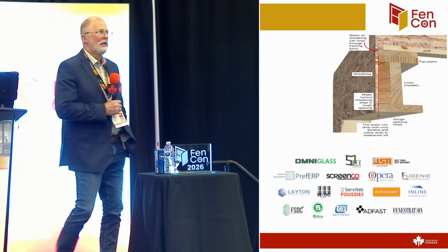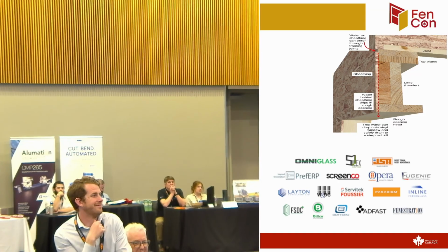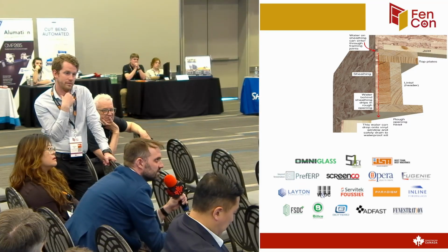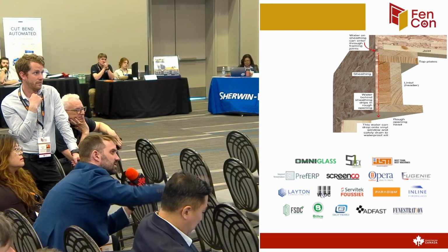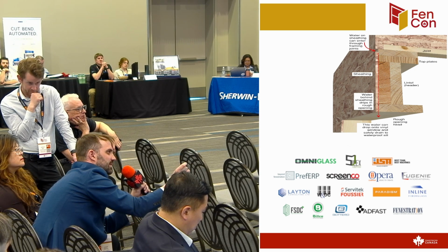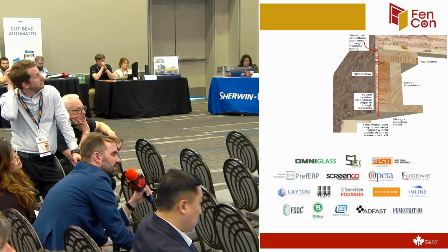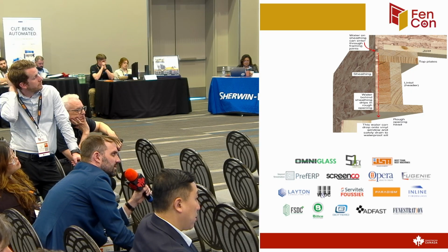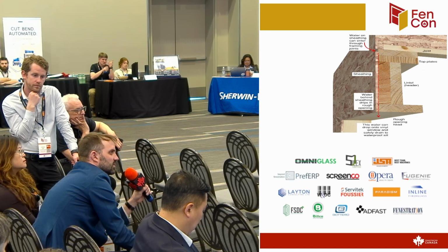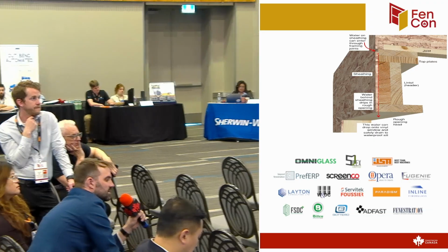Hey, does this change anything about what the siding crews do? Do we always expect water to drain between the plastic barrier and the siding and then out the bottom? It's usually going to come out at your weather barrier, so it'll come out at the bottom of the flashing. Is there any siding that doesn't work with that? Nope, it's always been that way, unless you do a face sealed system.